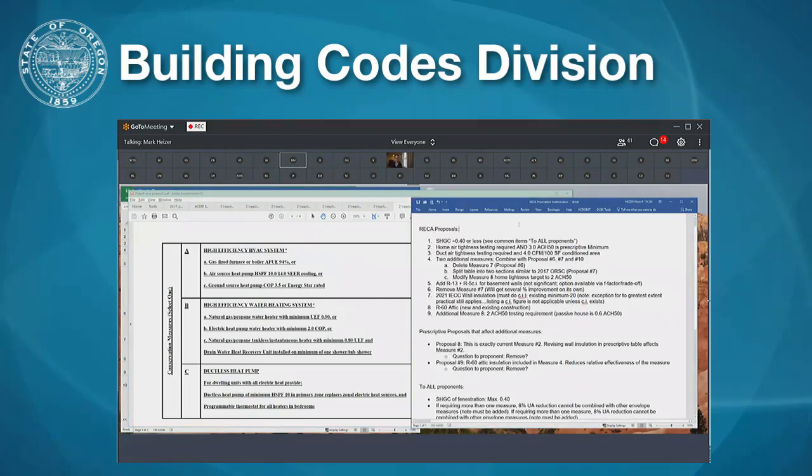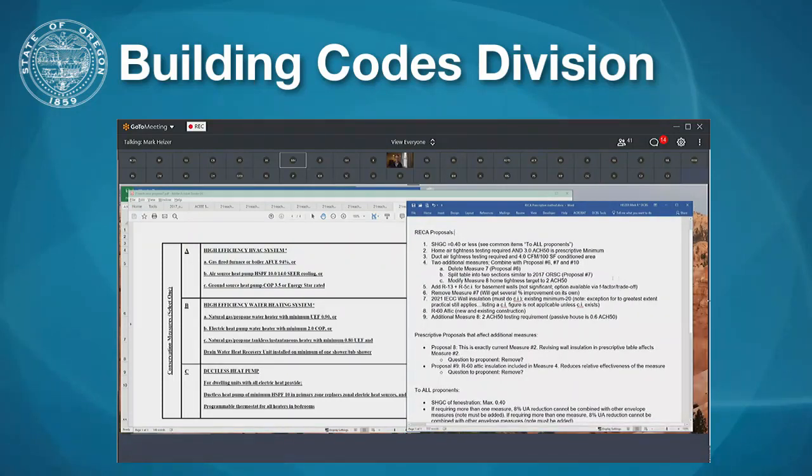Also, I wanted to point out another difference that you have, which is more alignment with the IECC, IRC about whole home air tightness testing. Model code has a requirement of whole home blower door testing to 3 ACH 50 as the prescriptive minimum, and this seems to be moving closer to that requirement and closer to what would be needed under the ZERH program for an above code project.